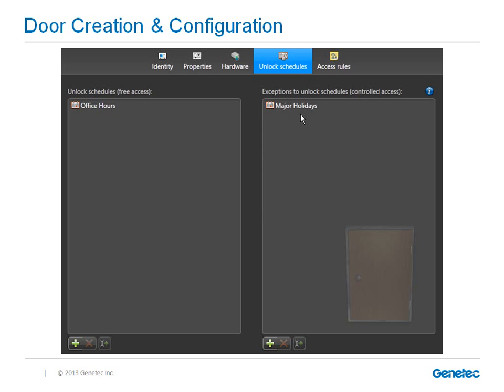Now, just a reminder of the schedule hierarchy. A more specific schedule will always override a more general schedule. So ranking them from highest priority to lowest priority, our highest is a specific schedule, then ordinal, weekly, daily, and our lowest priority and most general schedule is the always schedule.